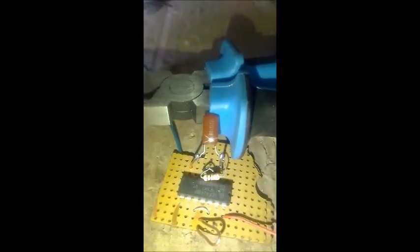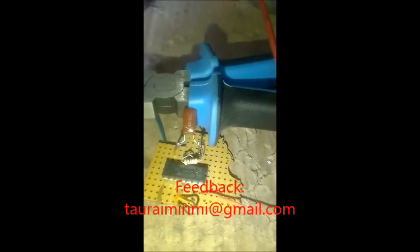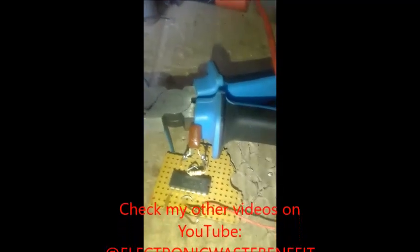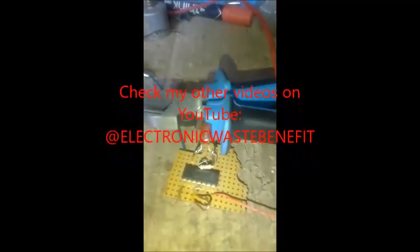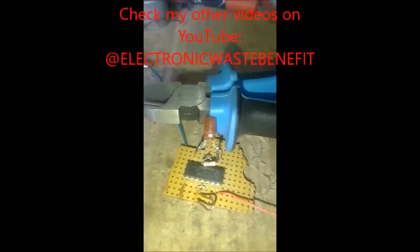Right, I've made this classic NAND gate oscillator. It's a relaxation oscillator using NAND gates. I've used all 4 NAND gates, but anyway, one is enough. It's a square wave oscillator. It uses a resistor and a capacitor on the input and output of a gate to produce a square wave. Right, I'm going to demonstrate how you can use a MOSFET as a capacitor.